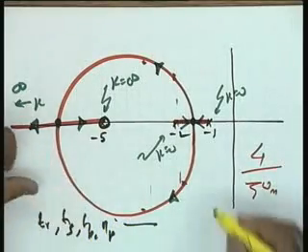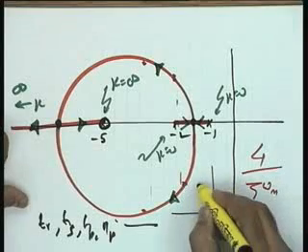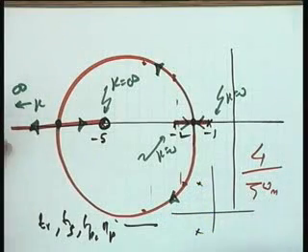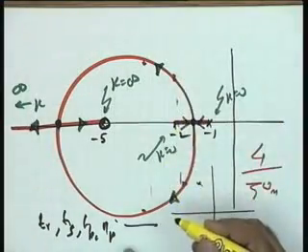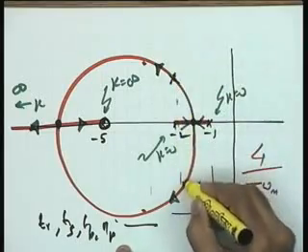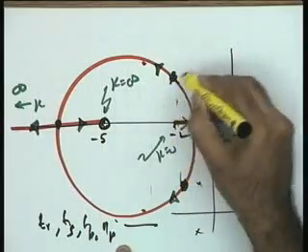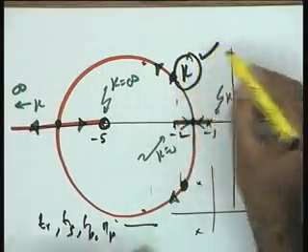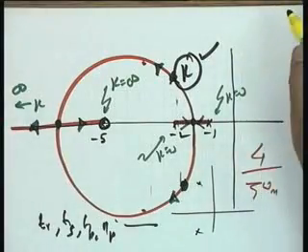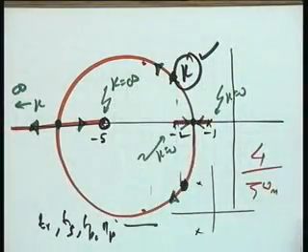Once these have been translated into two closed loop pole locations, what is the design after all? The design simply will be this: find out where the closed loop pole locations are. If these are the locations, find out the corresponding value of the parameter k, and your parameter has been designed. In this particular case there is no third root, so there is no problem of dominance condition.